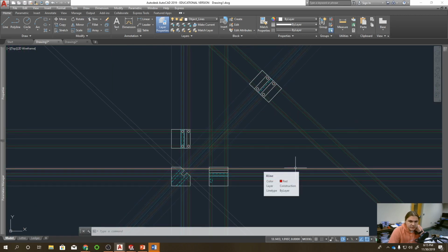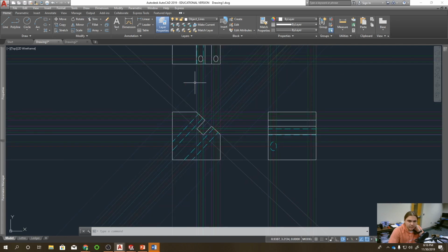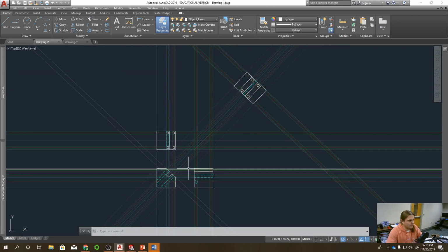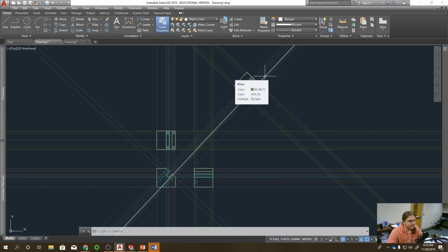And then the last step, just as you would do with your section views in AutoCAD, draw basically a cutting plane line, but it's a view plane line. Place it parallel to the inclined plane you're trying to look at, and put your multi-leader arrows pointing perpendicular to that line you just drew, pointing at the inclined plane you're looking at. And then with the text tool, just put A, B, C, D or whatever, and label this view here. I have this up here. We can move that down here, rotate it like I was doing in the SolidWorks file.